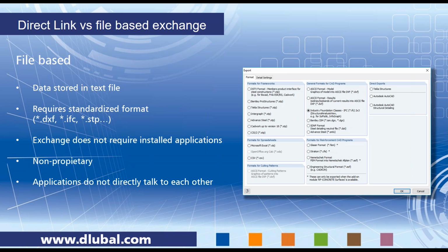IFC, for example, has no way to write for us nonlinear supports or information about load generation standards, a lot of information we just have in our software. So if this specification or the standard format does not provide a container for it, it's hard for us to write it there. On the other hand, it's an easy thing because we can just write a text file.